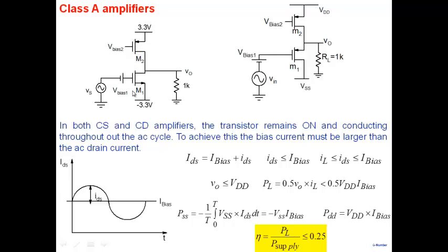So it's hot here. Now I'm asking my amplifier to work. Work means deliver power to the load here. Now a signal comes in and is delivering power to the load. What happens to the transistors? They become a little cooler, right? Because some of the power that was earlier being dissipated in M2 and M1 now actually goes to the load here. So the transistor temperature actually drops, right?